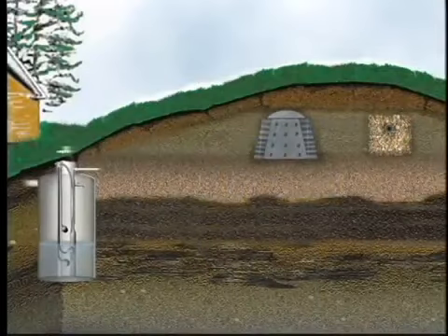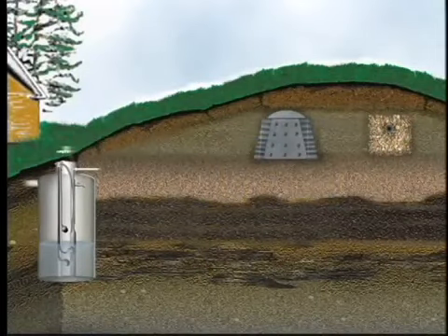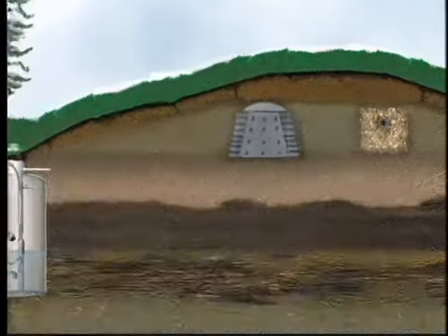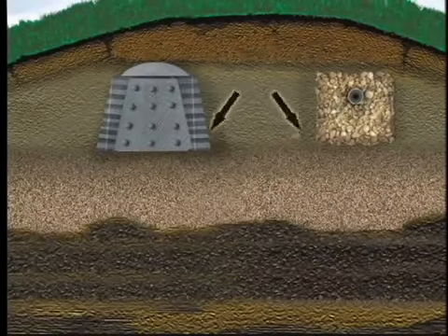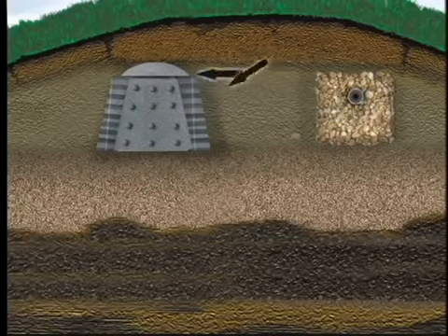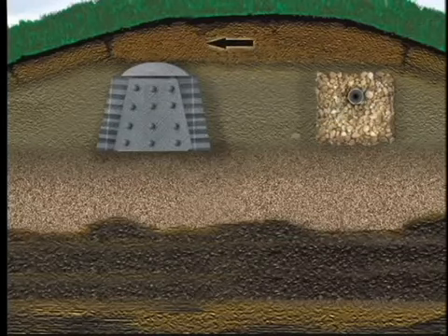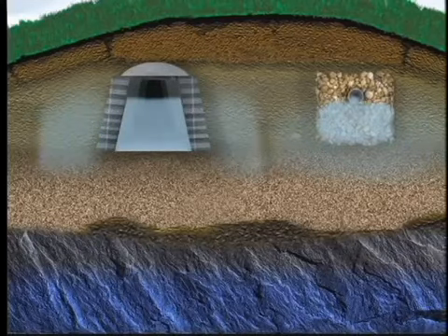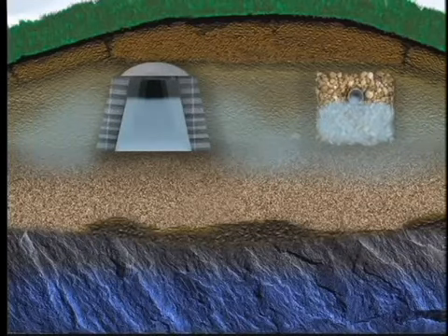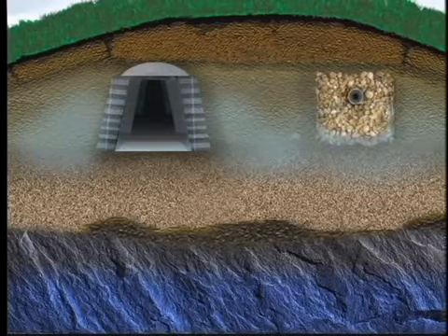A mound system consists of a pump tank and mound land application system. The mound has several layers including permeable fill material, a wastewater distribution system, a sandy loam cap, and topsoil. The mound system is ideal for areas with minimal soil between the surface and either groundwater or bedrock. A drain field is created above the natural soil surface to allow final treatment of wastewater.